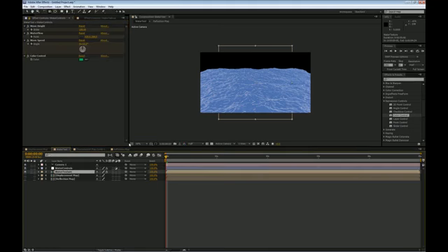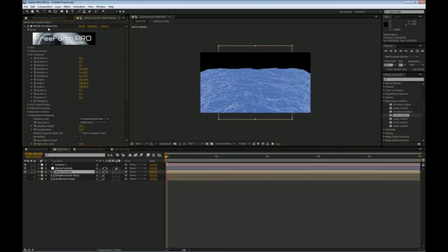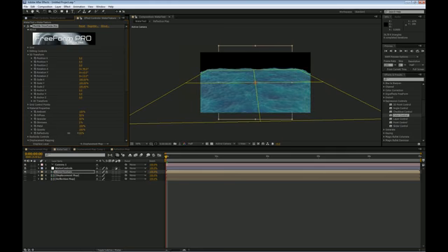If I go under water texture and go to my freeform controls, the material properties, if I bring down the reflectivity, you will see how the color of the water starts to come through. Basically, the color that you see here when reflectivity is 100, it's given by my reflection map, the sky, and the more I go down, the more of the color of the water texture comes through. So combining these two, I can get some really interesting results.